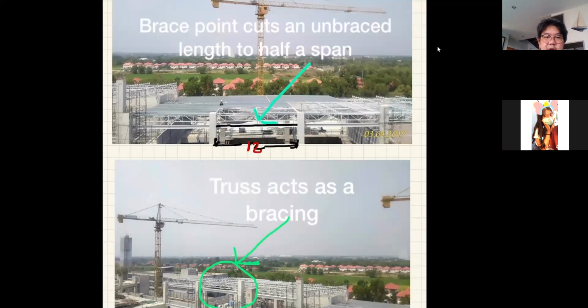And as far as we're concerned, you see this beam is completely in the air, so it is free to move laterally because there's nothing to brace except the point here where the truss is being supported by the beam. So this truss that you can see is standing on this beam, and as a result, it can help brace the beam from moving in and out of the plane.